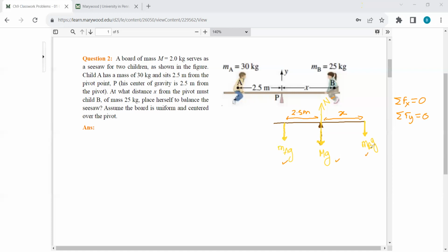So in this equation you will see that there is no room for this x. So by using Fy equal to 0, we cannot determine x, because Fy does not relate x with other known quantities. Okay, so the only thing we can use, I mean only thing we are left with is this one, tau equal to 0. So this is probably the equation we are looking for. Okay, so let's see whether we can use this equation or not. Okay, tau equal to 0.